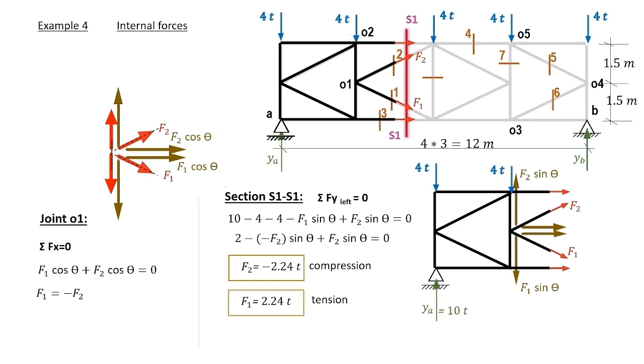To sum it up, to compute the two inclined members forming the K shape in a K-truss, we consider two equations. One of them, sigma forces in a certain direction at the joint. The other equation, sigma forces in the perpendicular direction for a section. This is not standard, of course. You can have any other method, but this was the method adopted here.